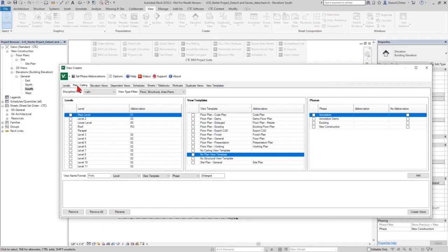In today's example, just for the sake of time, I'm only going to show plans and dependent views. You notice how these are named over here? Just alphanumeric naming. If you were to alphabetize this, which is what Revit is going to do when you throw it in the project browser, then the sorting is a little squirrely, right? You get level 10, 11, 2 through 9, and then lower, main, and roof. And that drives me nuts.